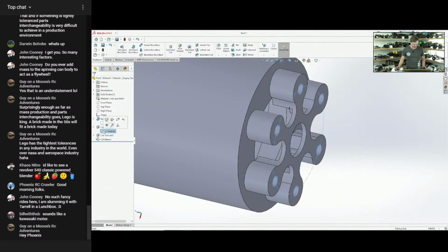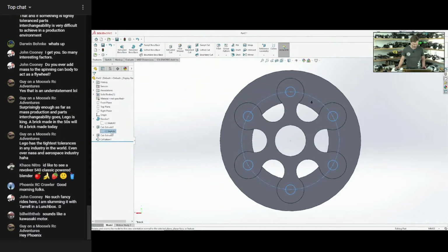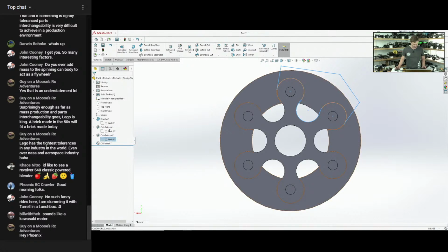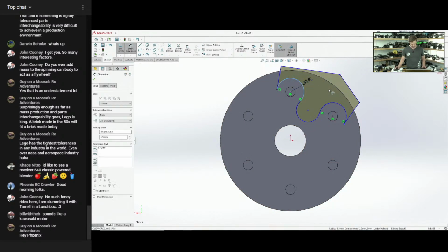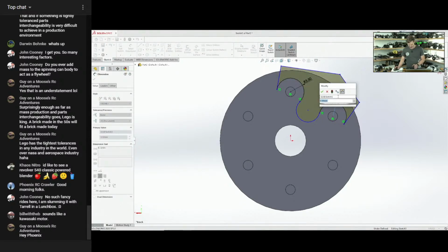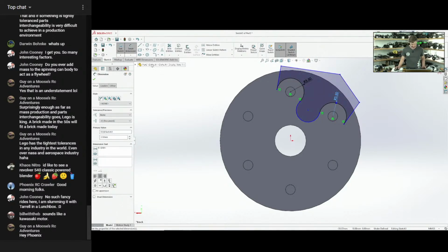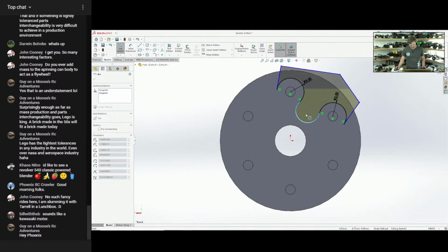I'm gonna adjust this a little bit. So we go back to our sketch. I'm gonna normal to, and wrong sketch. Whoops. We're gonna go back to our sketch cut. We're gonna normal to. We're gonna edit the sketch, and since I did not put any limiting dimensions, which I should, so that this doesn't do funky stuff. Okay, we're going to put those back at 3.5 radius, and now what I can do is literally just drag this around, and all right, I'm going to drag the center point.